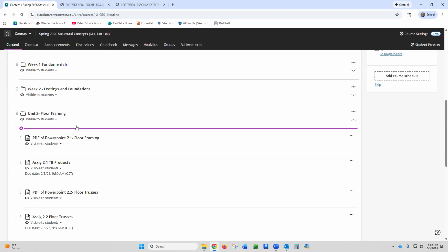Like it asks you for tributary area for beams. And if our tributary area is 13 feet and we put in 1 foot, which is the default number, our beam is sized 1/13th, like 8% of what it should be, and it would fail. The problem is you made a stupid mistake, but nobody knows it by looking at the report. They would have to have enough experience to know that they got the tributary area wrong on this.